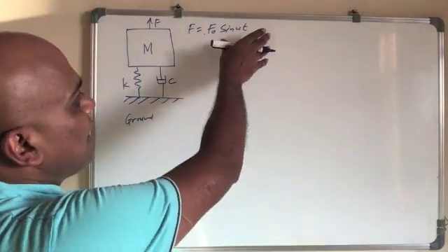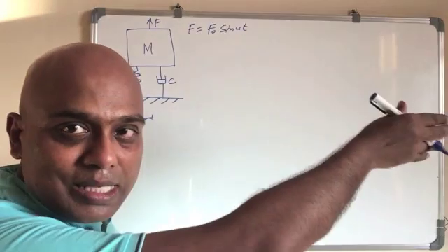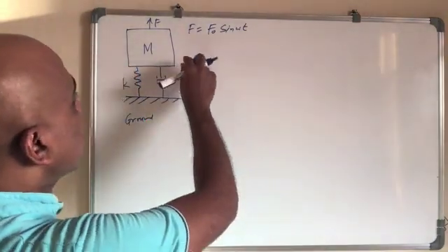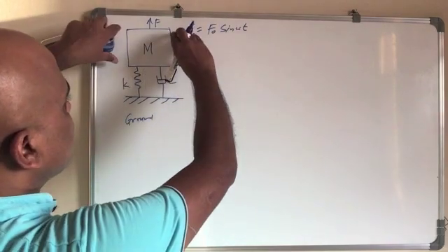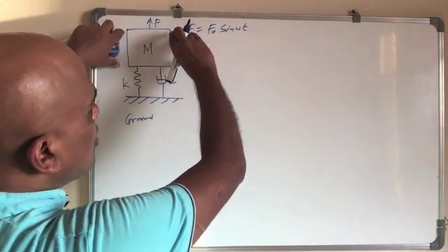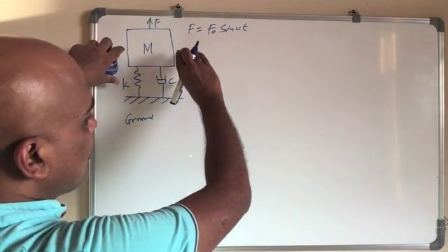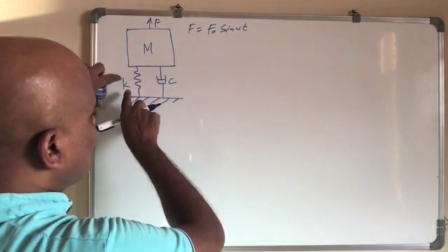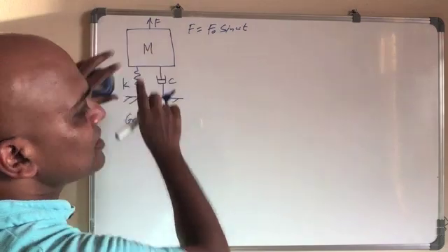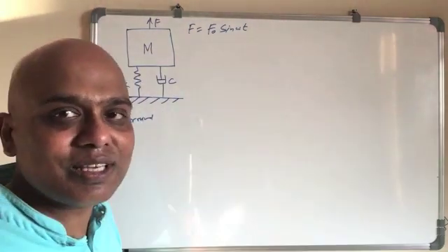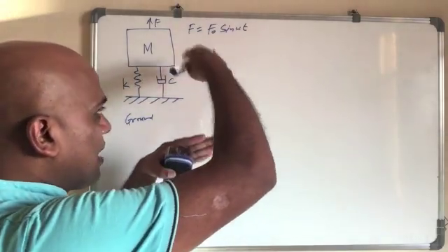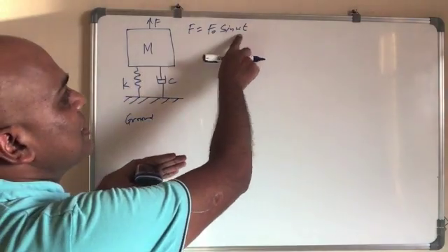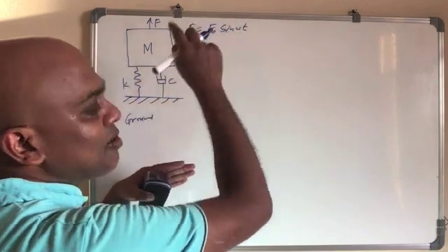So the static load we are keeping aside. Even if we consider the gravity, you know that in this case, this is going to go down until the spring displacement is going to balance the force, and that will be the mean position, and it is going to vibrate about that mean position if you give it a dynamic load like this one.